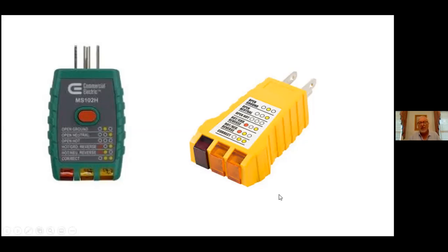I suggest somebody who really knows what they're doing with electrical. Or certainly, if you want to do the handy person type thing, make sure you do actually shut off the power at the meter or at the panel box, and make sure that outlet is certainly no longer active before you go in and start handling the electrical wiring. The one that we use would be similar to this.